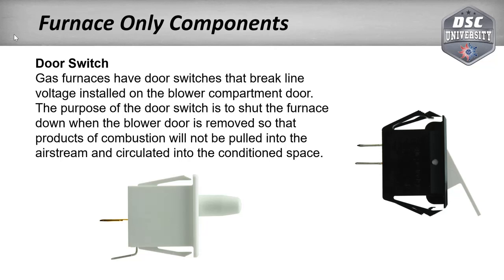So if this door were left off, then because we're sucking air in through here, it can actually suck the products of combustion from here back down into the blower assembly and blow it through the house, and we could have a problem with carbon monoxide poisoning possibly. So that's why we have that on there. It's typical, if I'm out working on a furnace, to take a piece of duct tape and tape the door switch shut, so while you're working on it, you don't have to keep putting the door on and off. Some guys will bypass them, but that's the reason we have a door switch on the gas furnace and not on the air handler.